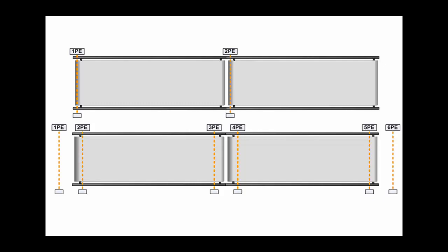We are going to write our logic for the upper pair simply because we do not have enough I/O interfaces on our controller to accommodate the lower pair. They both require 2 outputs for the motors, but the lower pair requires 6 inputs just for the photo eyes. We can't afford that. So we're going with the top pair, which is 2 photo eyes, and you have to be much more clever with how you write your code.